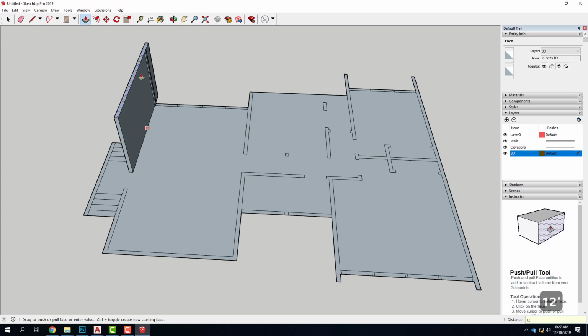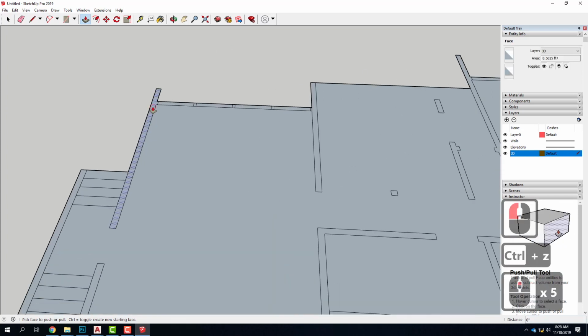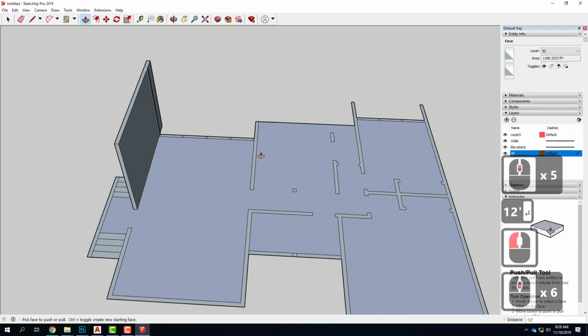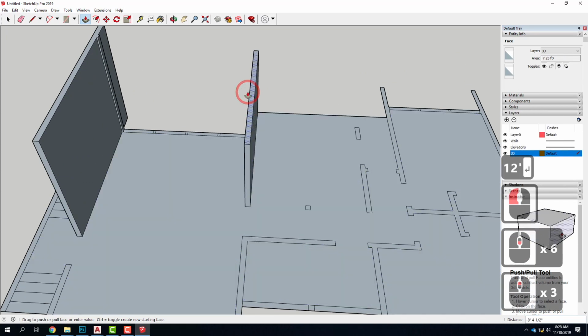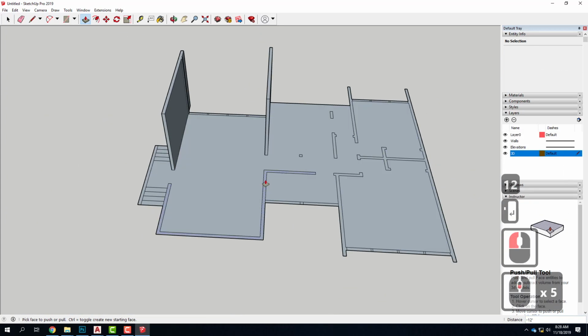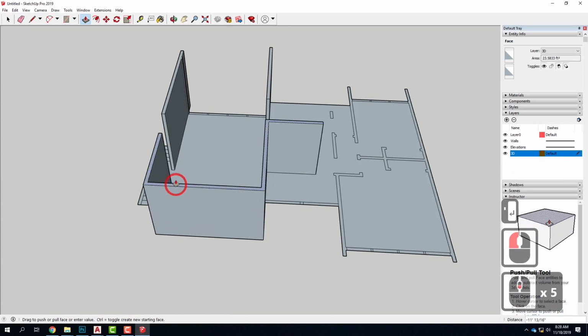And just like in AutoCAD, all I have to do is while I'm moving the object, type in 12 apostrophe. It's down in the lower right corner there. You can see the distance. Whoops, sorry, I didn't push enter. 12 feet, enter, and there it is at 12 feet. I could do it with this line, and that would be 12 feet, enter. There we go.